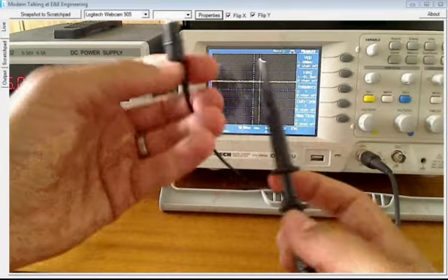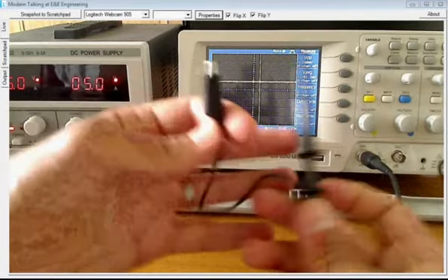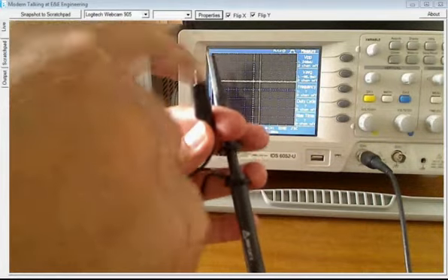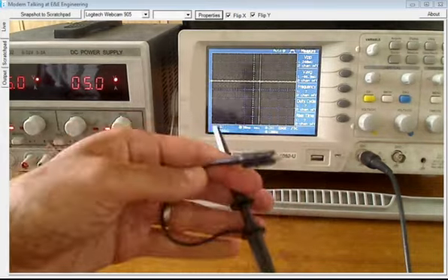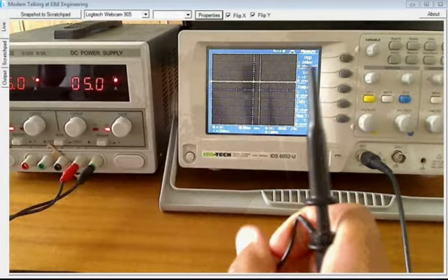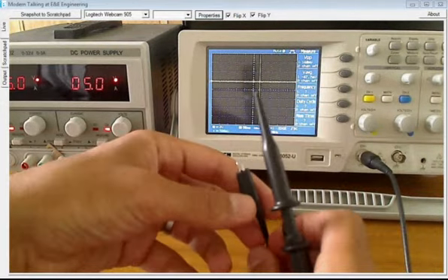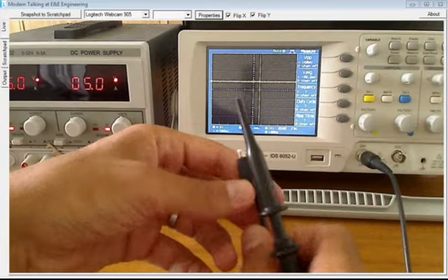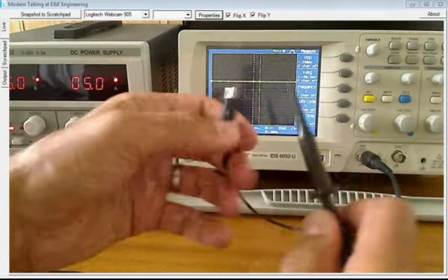That's the measuring. So one thing that is important to realize about scopes immediately is this crocodile clip here is connected to earth, to the earth of this chassis. And if you use a 3-prong plug to connect to your mains, then this will be connected to earth in some way.